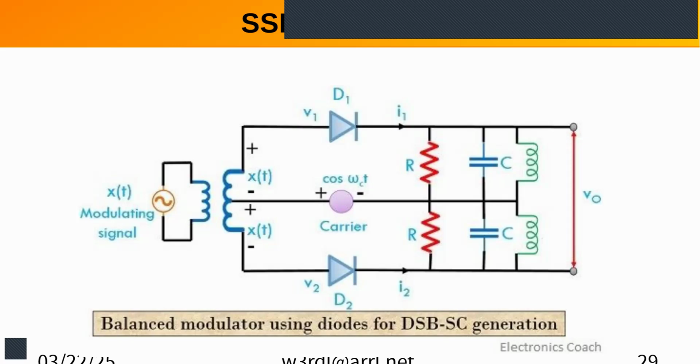So essentially the only thing you get out of it are the 2 sideband frequencies that are shifted up on either side of where the carrier would be, but you don't have a carrier, which is why it's much harder to tune in a single sideband signal because there's no carrier to lock onto. You got to figure out where it should be.